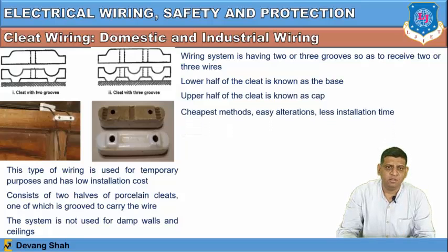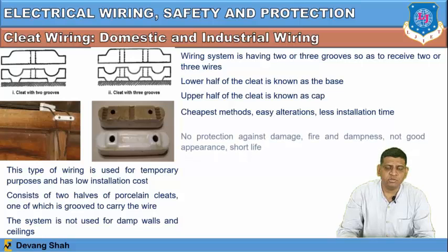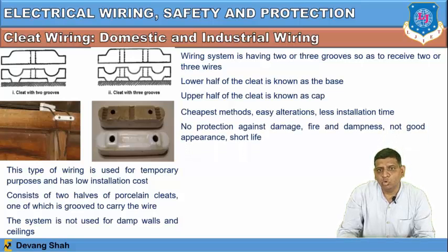Let's discuss the advantages and disadvantages. The advantages are that it is the cheapest method, easy alteration, and least installation time. But it has no protection against damage, fire and dampness, and it is not good in terms of appearance. It is just open in air, and it has a short life.